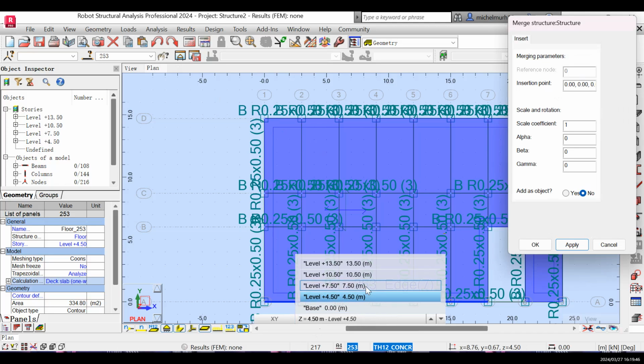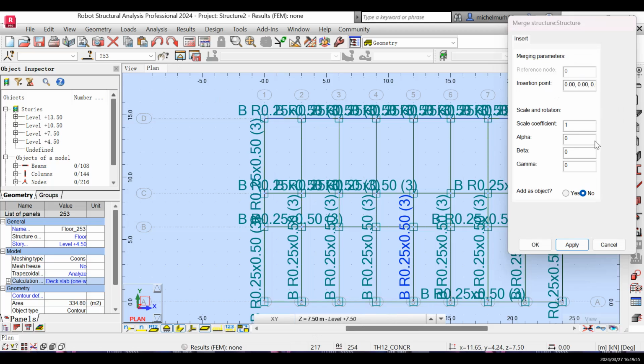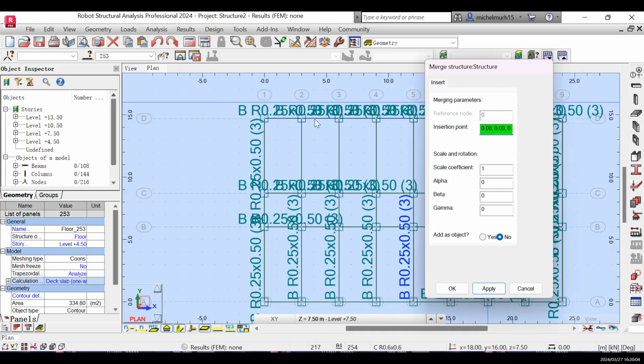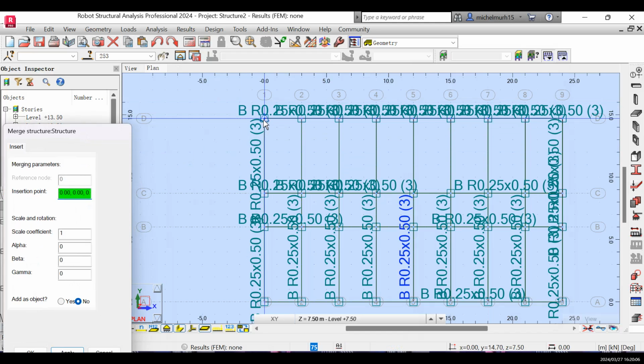And then after that, you need to change the view. Change the level from level 1 to level 2. Press on level 2, and here press on intersection points. The color is going to change to green, and you can move this. It doesn't matter. Make sure that the first point that you take is this point, and this point, and this point, and this point, and again the point where you started, this point here.